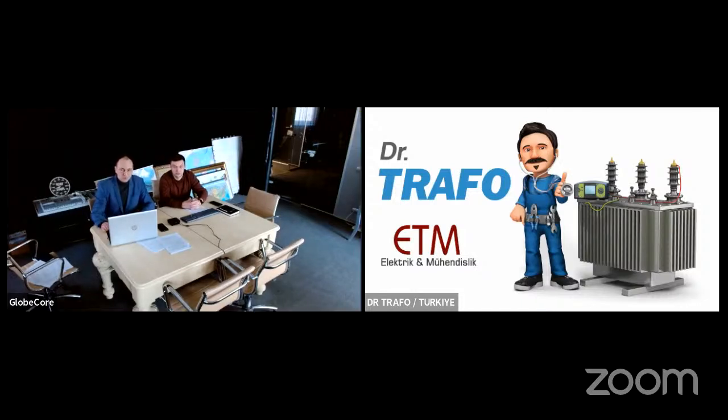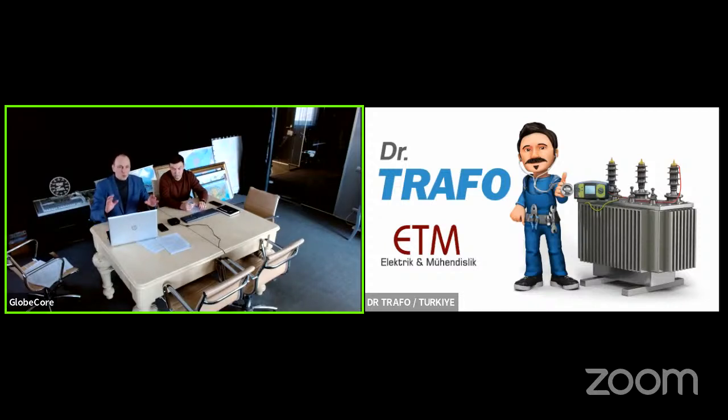At least may I learn your maximum capacity? For example, 1 ton per hour, 5 ton per hour. Okay, I will speak about our most popular regeneration system with 12 columns, with degassing section and with inhibitor injection unit. Usually we install a 12-column regeneration system plus 4,000 liters degassing plus inhibitor injection system. It means that in degassing mode, you will be able to operate with a capacity of 4,000 liters per hour.